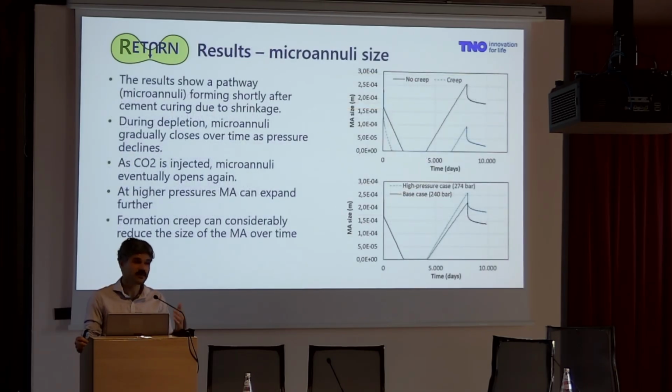In this particular case, we have a very overpressured caprock, and we actually anticipate a microannulus, a pathway in the cement opening as the cement is curing due to those initial conditions or stresses in cement. So the cement density here is particularly, and the length of it is not high enough. However, as you start producing this reservoir down, you actually close that gap. So again, this is the dynamic part of the leakage pathways. They're not always open or the same size. They actually evolve over time.